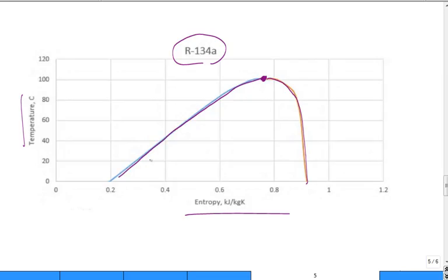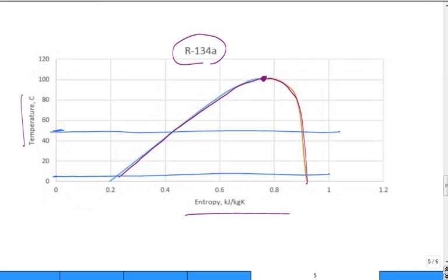All right. So where was our temperature at which the fluid was condensing in the condenser? It was around 52. There's close enough to 52. Boom, there you go. What was the temperature that we, for our problem, had an evaporator? About 4, right? No, this is 20, that's 4, there's 4, close enough. So on to scale, this is to scale. Where is state 2? Where is state 3? Where is state 4? And where is state 1?